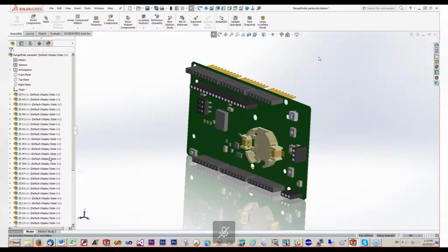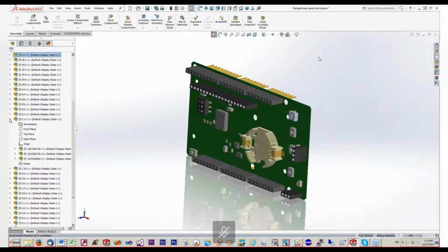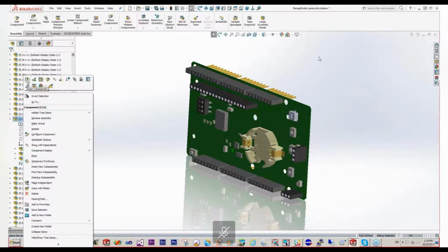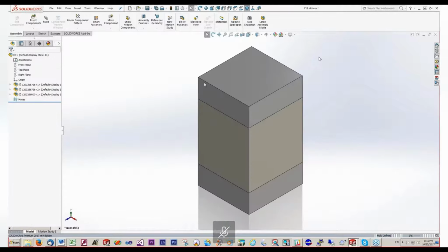If you're not familiar with SolidWorks, SolidWorks basically works in two different types of entities. I don't want to call them primitives because it's not really primitive. You either have what's called an assembly or you have a part. And if you're looking at the left side, what this did was it came in as a bunch of assemblies. Okay? So graphically it's fine, but in terms of its intelligence to make use of it in the traditional form of looking at, let's say, a component, it didn't really come as a component. It actually came in as three separate entities.